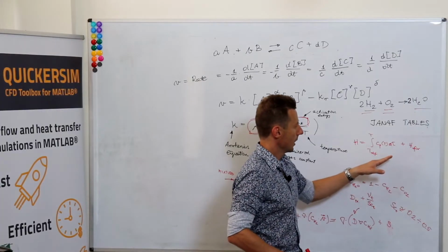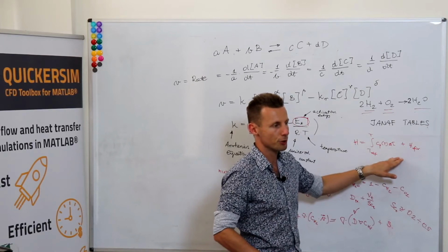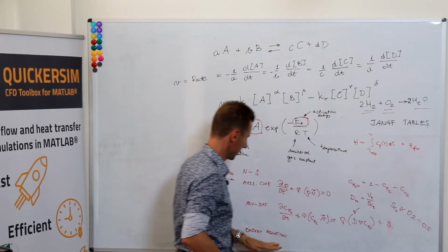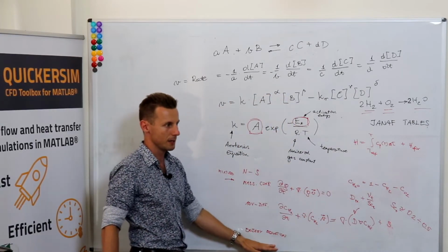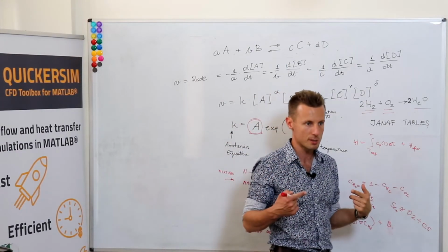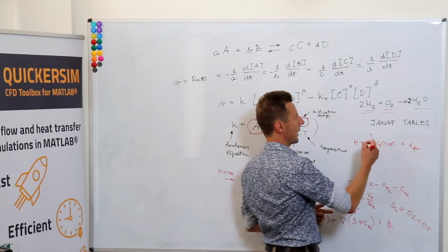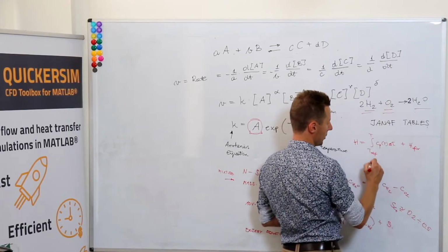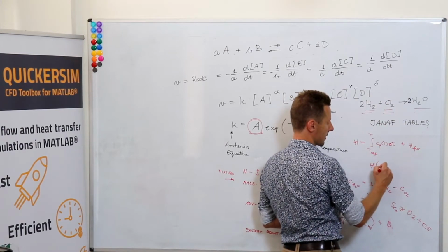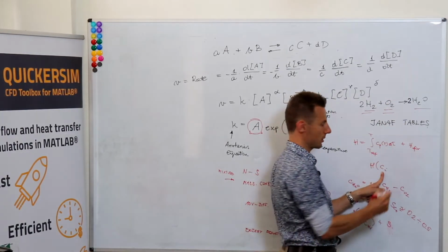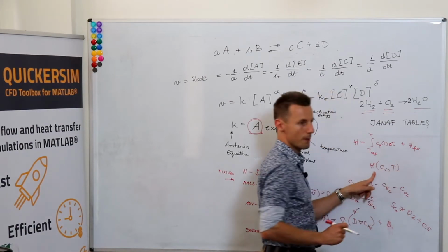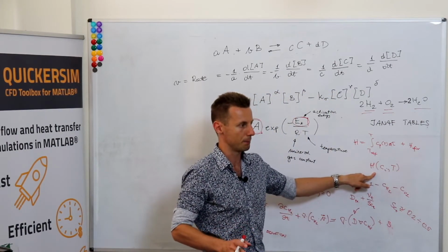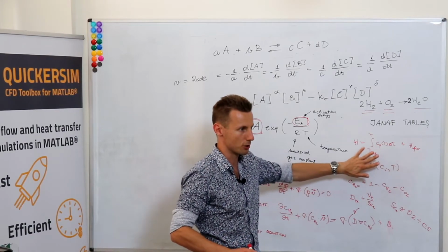And as far as I remember, you don't need to put it into the energy equation in CFD, because for the whole mixture you've got all the concentrations and the temperature, and this constitutes the total enthalpy of your mixture.